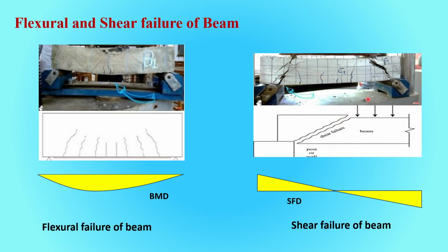So this shear failure is to be avoided and flexural failure is desirable. It is a comparative word. When we say we want flexural failure, it doesn't mean that we always intentionally want a failure. No. When failure is inevitable, then we want that our flexural members should fail and not the shear members or the compression members.